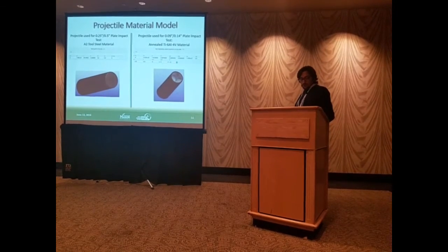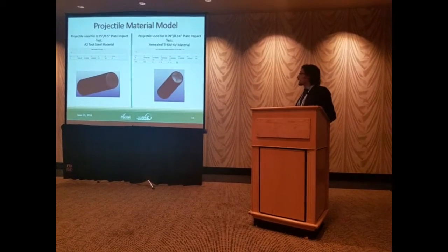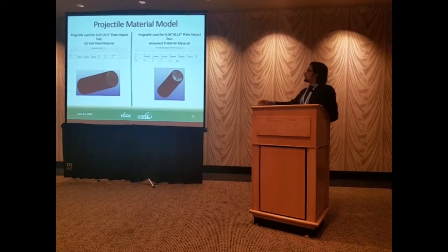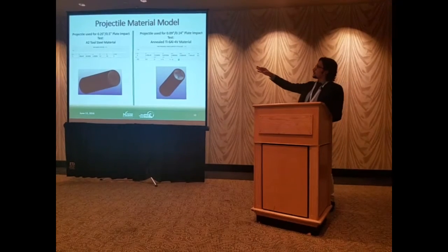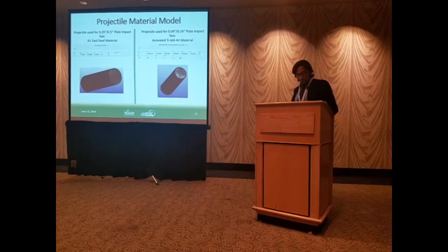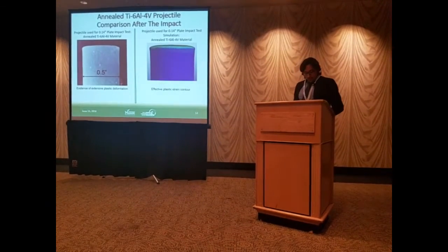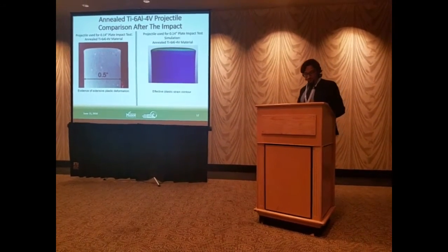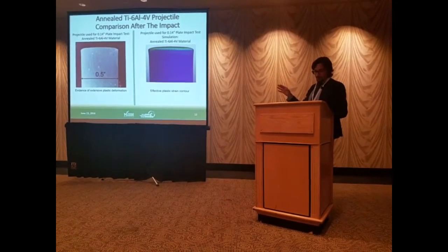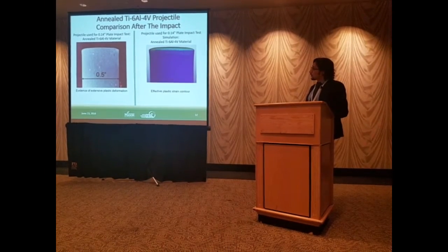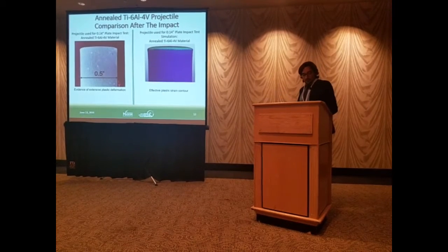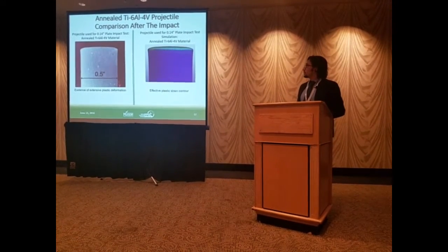So here you can see the material input deck used for the projectile, and the difference for half-inch, quarter-inch, 0.09 inch and 0.14 inch. And here we have a comparison of the deformation after the impact, just for the 0.14 inch plate impact test, where we match the plastic deformation pretty well.